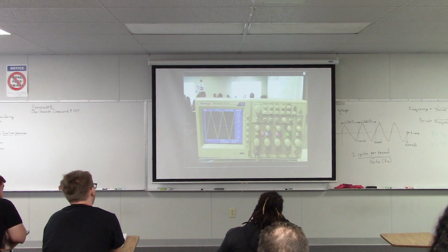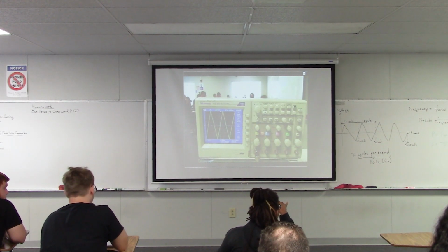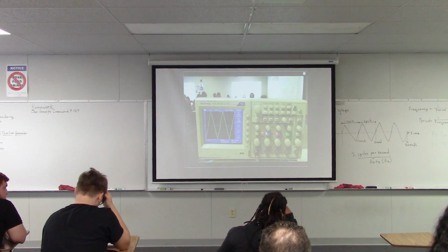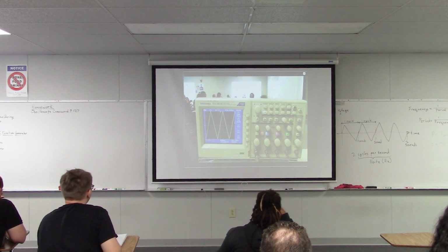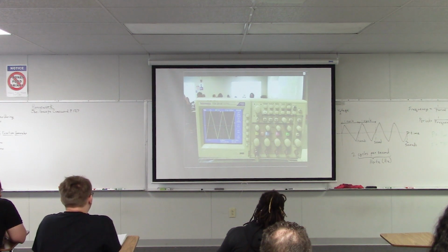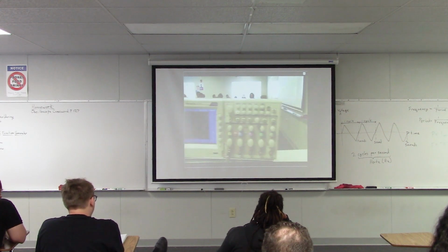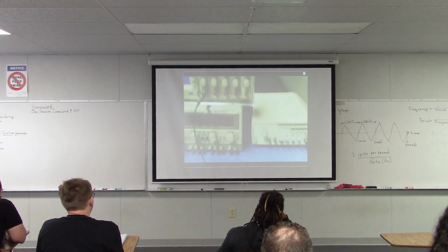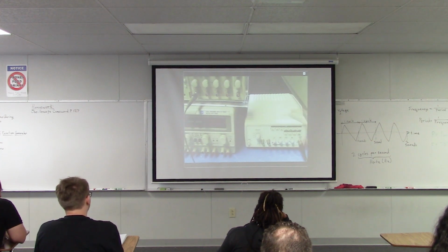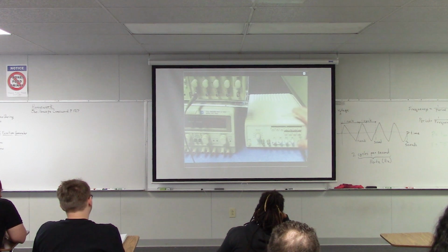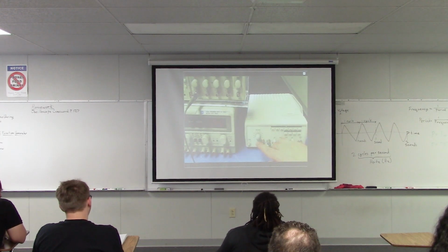Yeah? Can we go over again how you got the period to 1 millisecond? Yeah, so how I calculated it, or how I set it on the actual signal? How you set it on the signal. Okay, so what I did is I played around with the controls on the function generator, because remember the function generator is the instrument that's actually creating the signal. So what I did is I put the generator in the 1 kilohertz range, and then I set the frequency knob to about the 1 position. So then the frequency is just 1 times 1,000, or about 1,000 hertz.